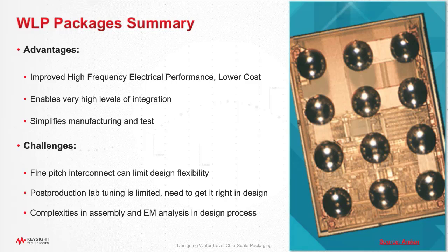The other thing is post-production lab tuning is pretty limited. That means you've got to get it right in the design. I've done it on boards and laminate types of packages. I've taken little X-Acto knives and shaved traces or cut traces, inserted components. I've even, on chips, taken diamond scribes and brushed down inductors to get rid of a big inductance to fix a stability problem. But when you have everything packaged up on the wafer, you're not going to be able to go in and start hacking away at your design. It's really important, and it's going to take more time in the design phase to get it right.